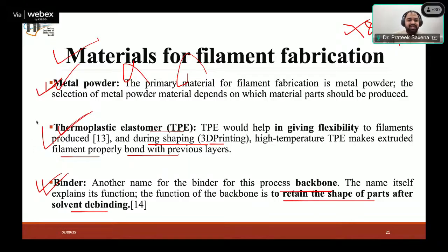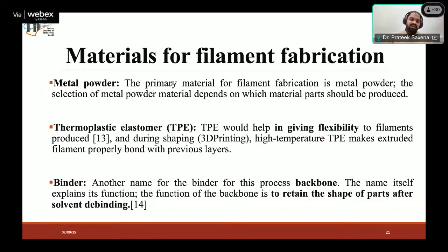There is also one more thing that I haven't told you until now. There is one more advantage to this kind of approach. Let's say I have made a cube, and when I have dipped that cube into a solvent, partial debinding has happened, something has gone out. A good thing is that whatever has gone out would have created some kind of escape routes, some kind of channels, also at the interior and also at the top of the surface or on the sideways. And these escape routes, these tunnels, will easily allow the binder to go out.